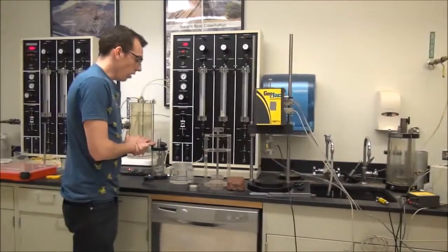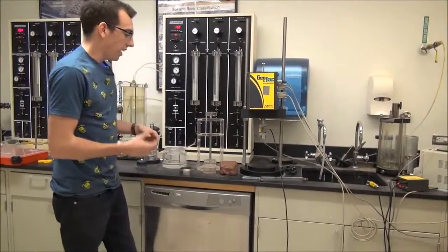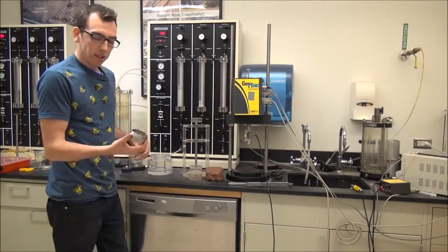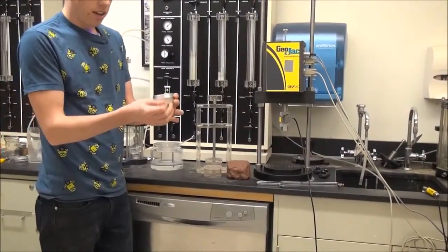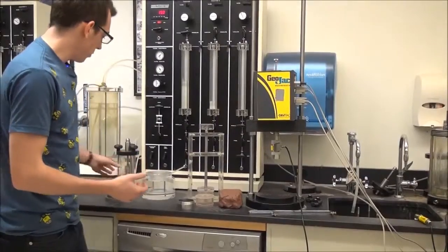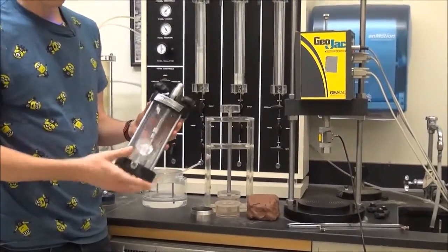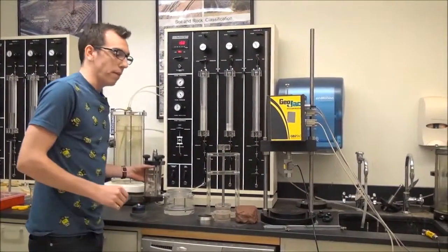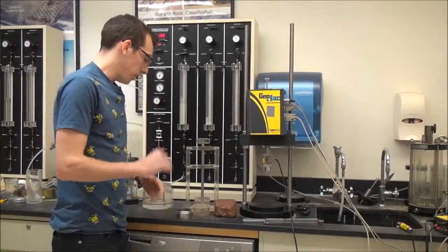So what we'll be doing is we will be preparing a sample for a confined consolidation test. When you do a confined consolidation test, we'll have a sample in this metal ring of known diameter and volume to begin with. There's other tests like the triaxial test, where you have a cell with water in it that you can control the pore pressure, and that adds another dimension of analysis to the test. But we'll just be doing the vertical displacement.